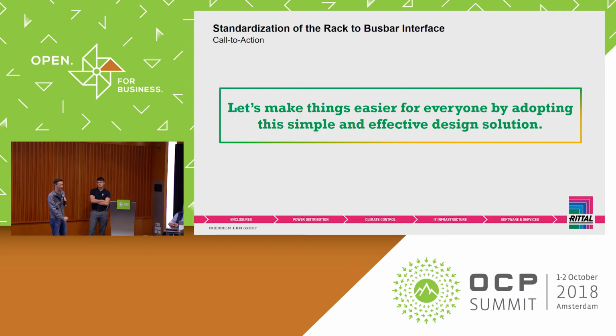I think the only problem we've got right now is if you've got a 1U shelf, the holes are not really aligned very well for a 1U shelf. Anything bigger than that, it works fine. So we're in the process right now of making that tweak. This last year we could not use the light on the power shelf. All I can tell you is there are dimensions in the spec for both the rack. It'll tell you exactly how far away it's supposed to be from the U position, so you could measure and figure out which one is not complying and giving you that problem.